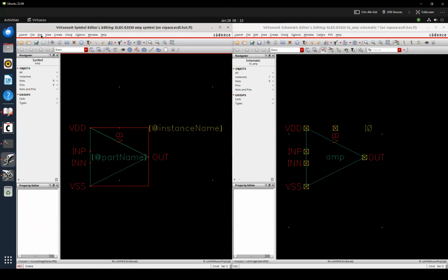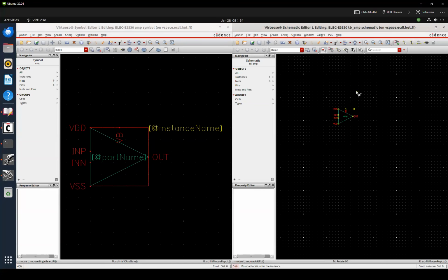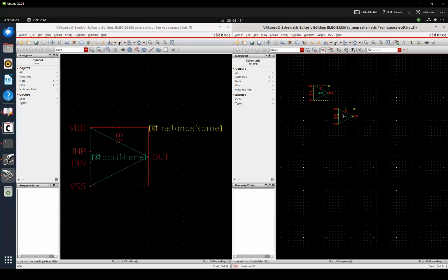And you should also put the origin close to our amplifier side. This will make sure that when you add an instance, it will follow your mouse pointer. So what I prefer is to put the origin at the VDD node. Or you could put the origin at VSS, output, input, or even the center; this is also fine. So if I instantiate, now you can see that our mouse pointer is centered on VDD, and the selection box is more compact.